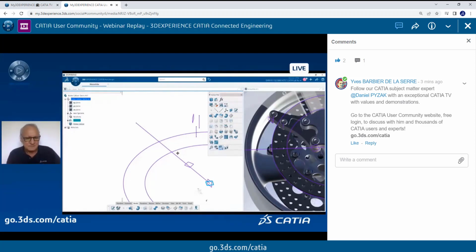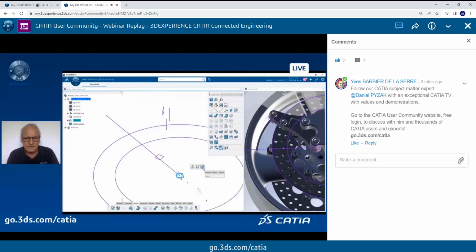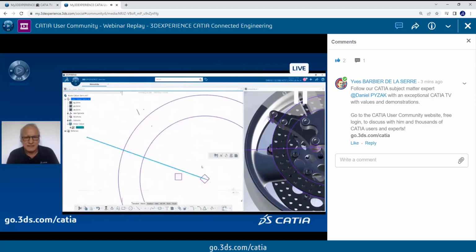Probably you want to do a sketch. And I say yes. So I don't have to go and click on the sketch icon, which might be somewhere, maybe in my action pad or maybe not. You see here, sketch. Now I'm defining my sketch, and all my commands of the sketcher are also popping up in front of me, close to my mouse location and my click, and proposing to me some commands depending on what I clicked. This is what we call the contextual immersive commands.